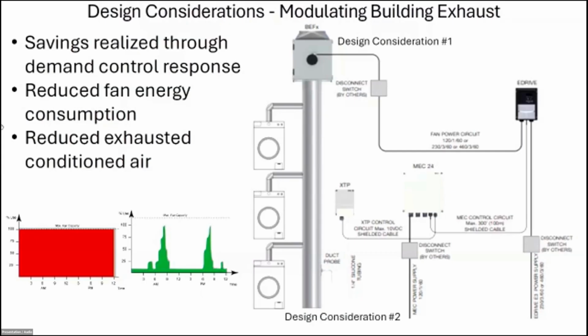This is air that we have conditioned. We have spent money and energy, make it warm, make it cool, humidify, dehumidify, whatever. We've spent money and energy to make this air in these spaces comfortable for these people. Needlessly drawing it out of the building with a constant speed system is just a waste of energy.